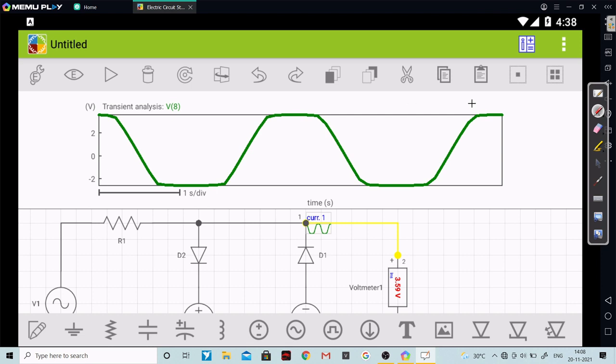Over here it should be plus 3.7 volts, and the practical value we are getting is roughly around 3.6 volts, so I think this is absolutely fine. This is when our input voltage was greater than plus 3.7 volts. And if you look very clearly, we are getting minus 2.7 volts, and the rest of the waveform is getting reflected as it is to the output side.